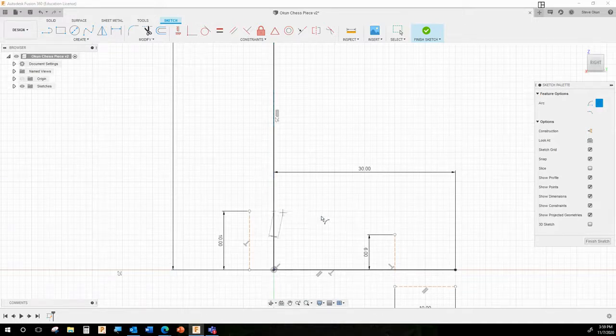And then I'm going to let go of my mouse button and just drag my mouse over. I'm not going to stop here. You don't draw the arc the way you would draw it with a pencil. You draw the 2 endpoints first. So I'm going to draw one endpoint, and I'm going to come over here. It's just telling me how far apart the endpoints are. Don't worry about that. That might be something I need to know, but not in this case. I'm going to make sure I'm right on the endpoint of the L here, and I'm going to click there.